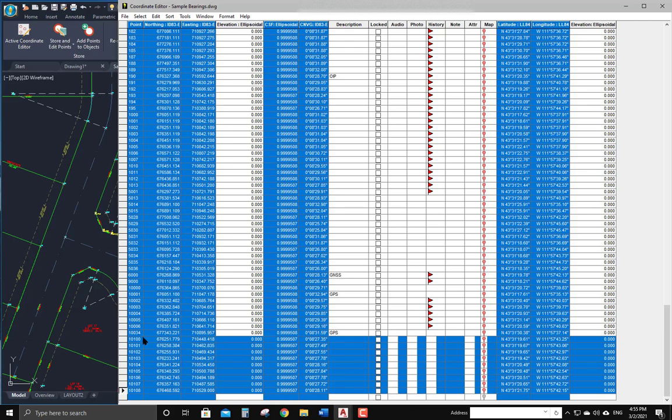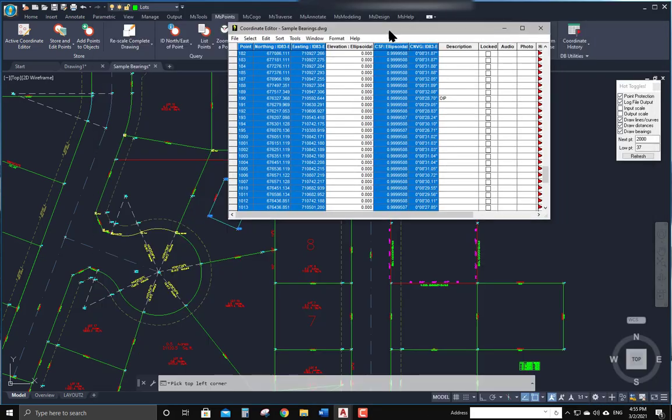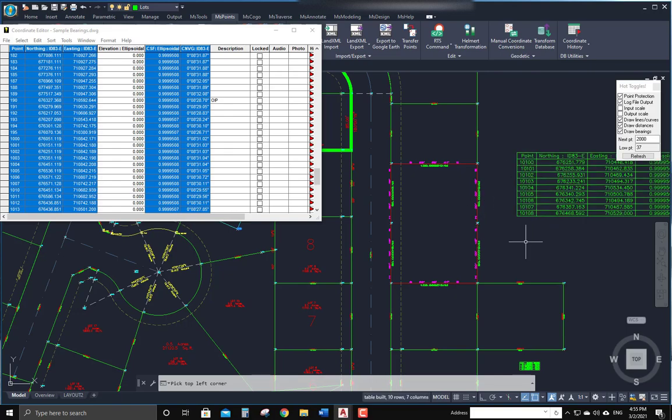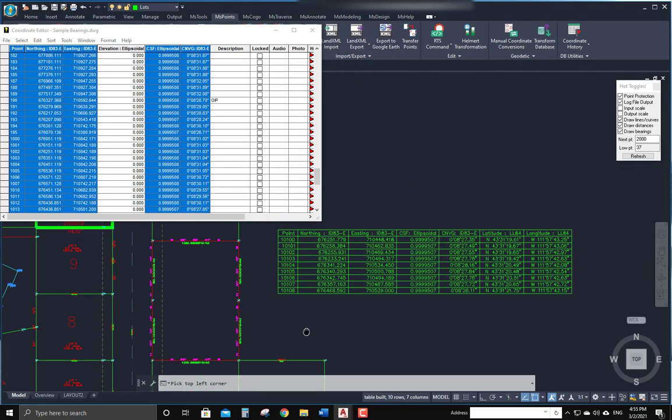And so I'll be creating a table consisting only of the items that are overlapping in this selection. So go back to Tools, and we do Table in Drawing from Selection. And so now it's just going to prompt me for a location for that table, and I might as well just put it right there. And it's computed all the values and plotted them right in the drawing.